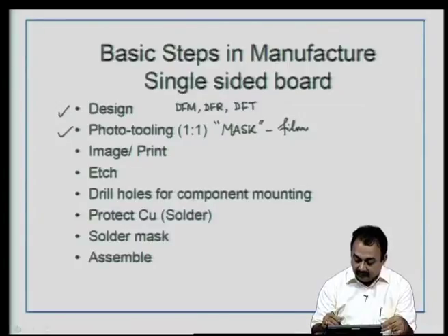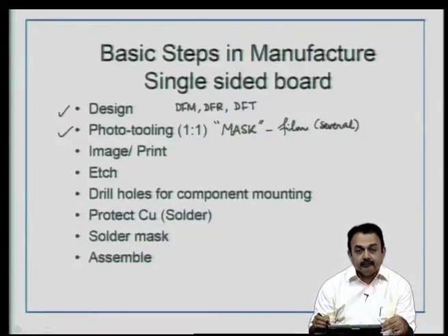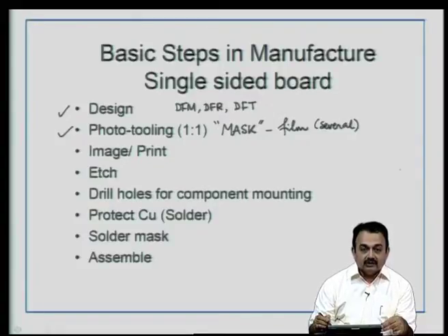So, you may have to have several masks for a multi-layer board. For a single sided board, typically you will have one electrical layer and therefore, a single mask, but at the same time a mask for a solder mask will have to be created and a mask for a legend print have to be created.